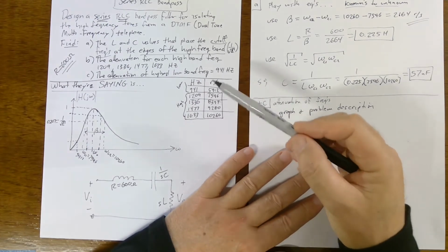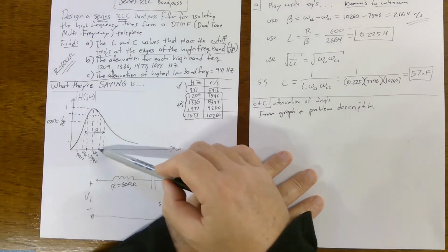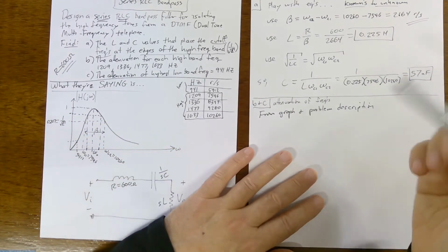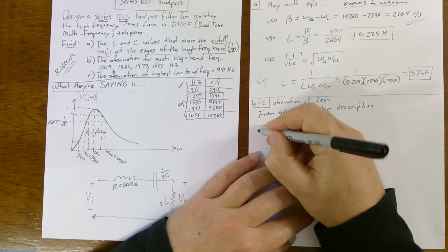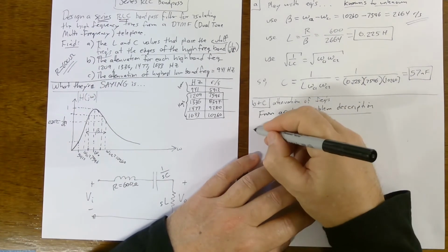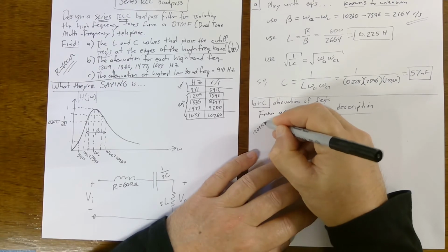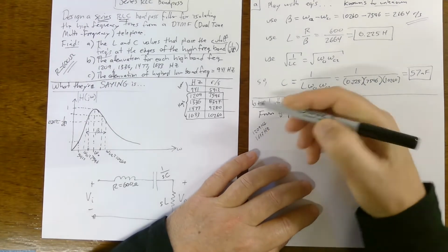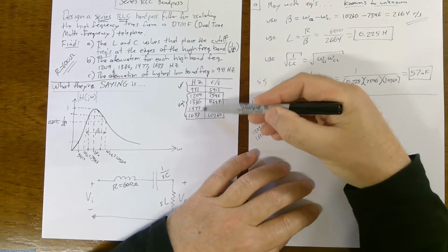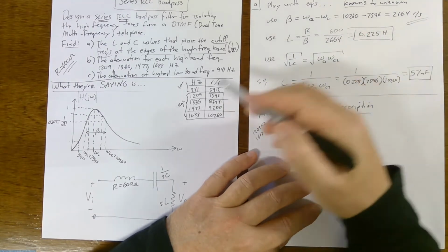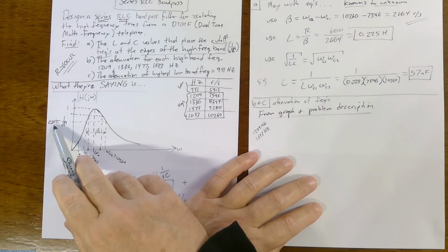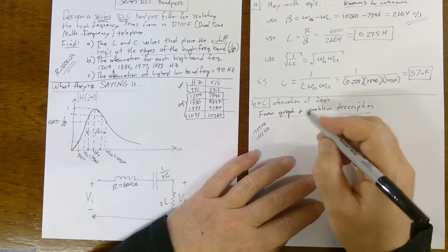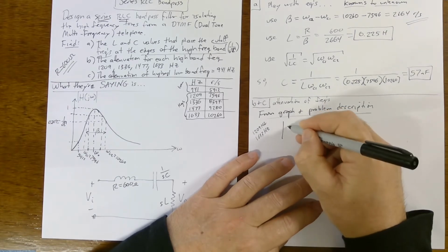And the definition of a cutoff frequency is the frequency at which the attenuation is 0.707. So the answer, you have two answers already. So for 1209 hertz and 1633 hertz, the two cutoff frequencies, the attenuation is 1 over root 2, because that's by definition.